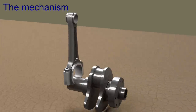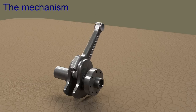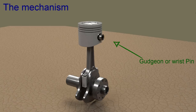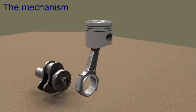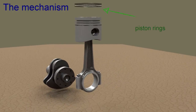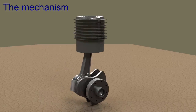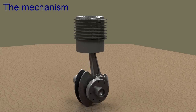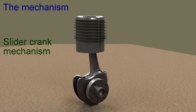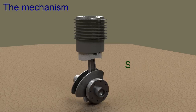The big end of the connecting rod connects to the crank and can freely rotate on the crank. The smaller end of connecting rod is connected to piston using gudgeon pin and connecting rod can swivel around the gudgeon pin. Piston is placed inside the cylinder so that it can have only sliding motion in one direction. The resulting mechanism is known as slider crank mechanism. It converts linear motion of slider into rotary motion of crank.